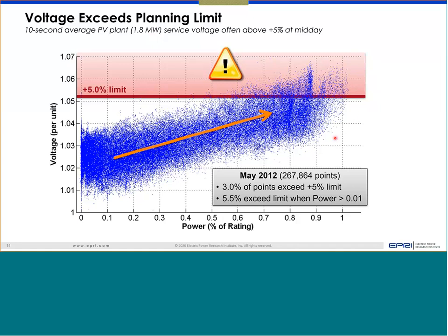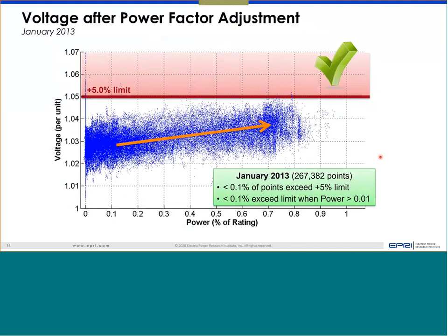In that particular case, the utility had an agreement that if needed, they could ask the plant owner to change the power factor. After changing the power factor in the absorbing direction, there was an error in the middle, which we are not showing in this figure. The technician went to the site and, rather than absorbing VAR, accidentally selected VAR in the injection direction. So again, the plus minus confusion. There was a period where the plant was actually injecting VAR and pushing the voltage even higher. You can expect it was already high, and now pushing VAR pushed it further high.